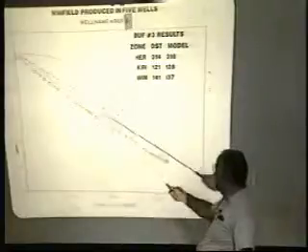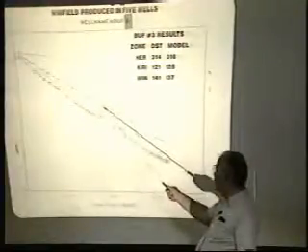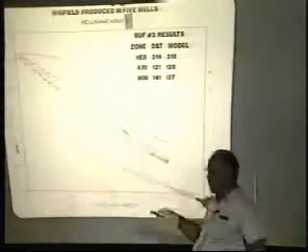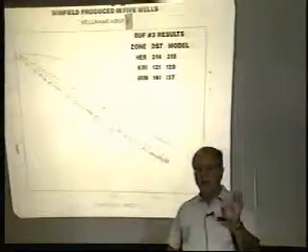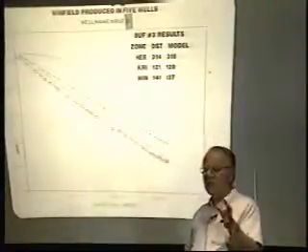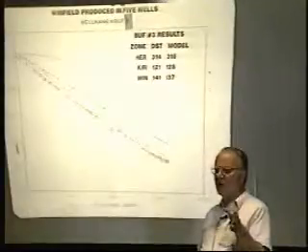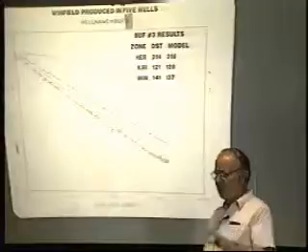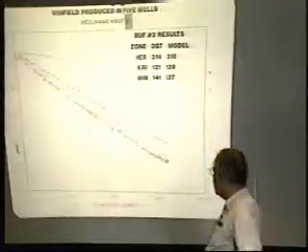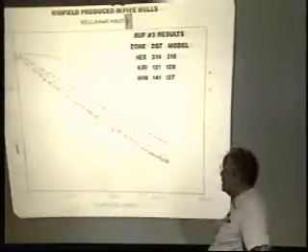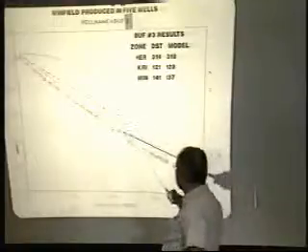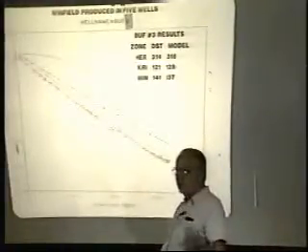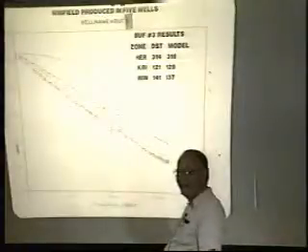The red dots, the reason you can tell the red dots are field data. We have a 72-hour annual test that consists of a 72-hour shut-in pressure and a 72-hour drawdown. After you shut it in, you flow it for 72 hours. You measure the rate and flowing pressure. You also got the shut-in pressure before you turned it on. So that's where the red dots are squares, and people who are colorblind can't see them.